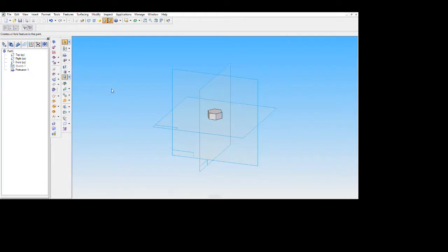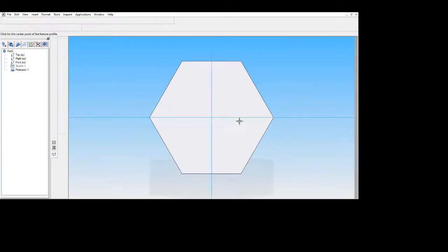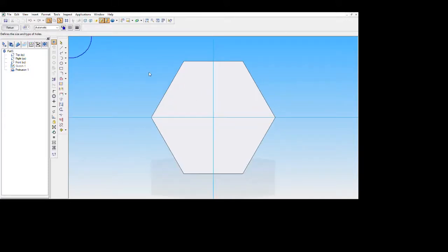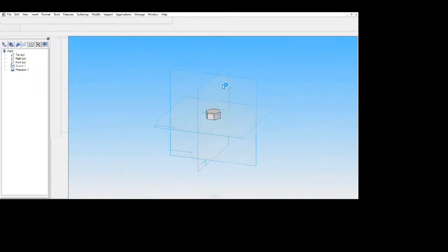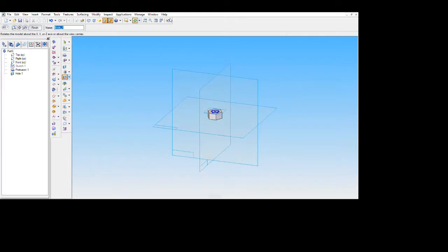Go with the hole command, select the top surface of the nut, go to the hole properties, select threaded hole, give the diameter as 10 as it is given M10, go to the hole extent, even the thread should be of hole extent, click OK and place the hole at the center. Go to return, select downwards. Now you can see the hole is formed with the threads.